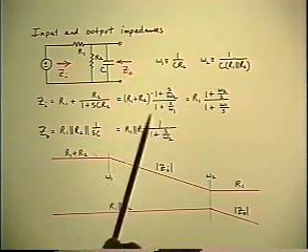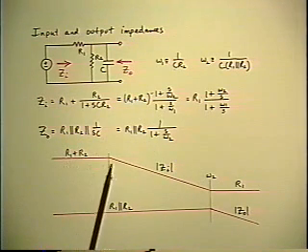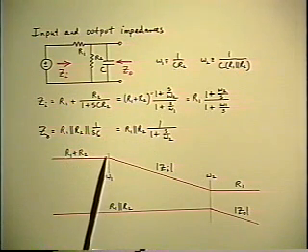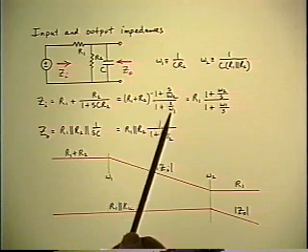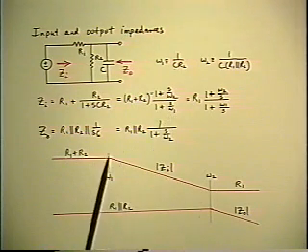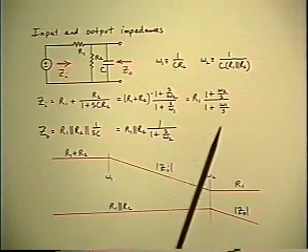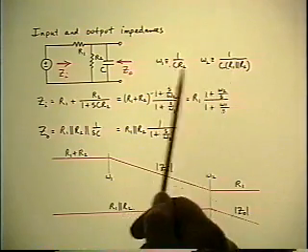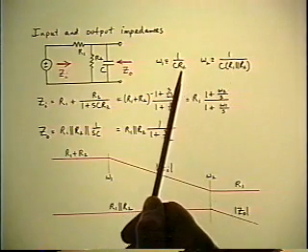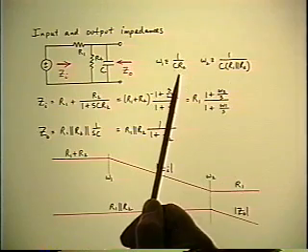Using the normal pole zero form, the reference value is R1 plus R2 at zero frequency. As frequency goes up, you get to the pole or the zero, whichever comes first. Looking at the expressions for the pole and the zero, obviously the pole must be lower.